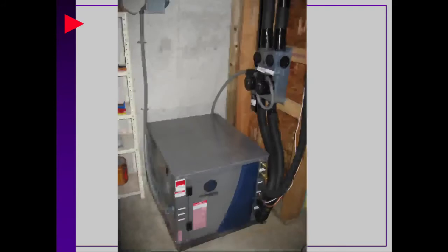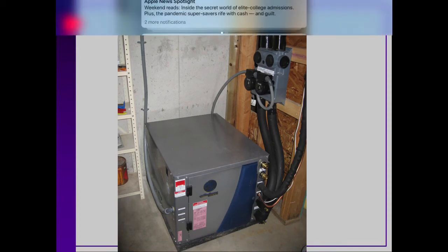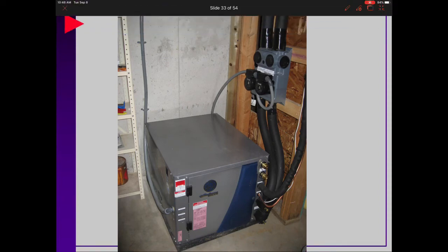So this particular little heat pump system is showing a split system. What they're doing here is they have, inside this WaterFurnace unit, a compressor and a coaxial coil with a de-superheater loop. The de-superheater loop that would be shown here, let me change that, would be right there.